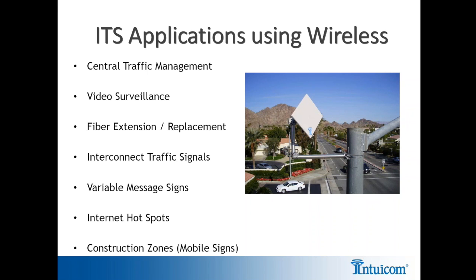It is simple to install and has long-range, non-line-of-sight performance. These 900 MHz solutions are the perfect way to bring online standalone intersections in closed-loop traffic management systems that do not have Ethernet-enabled controllers.